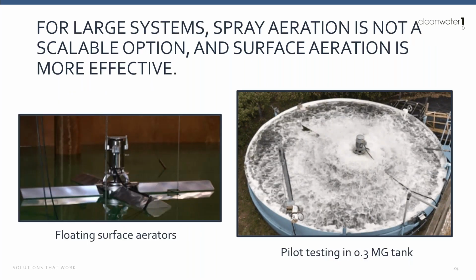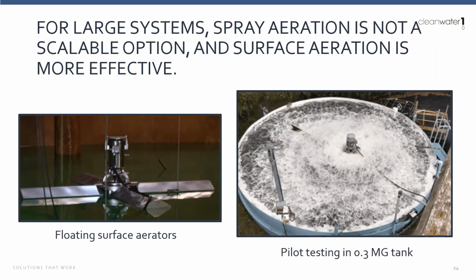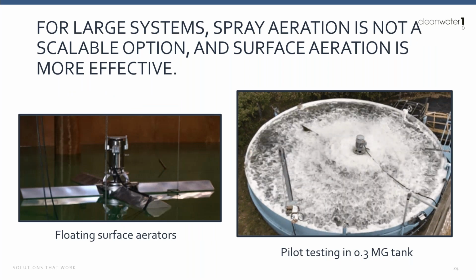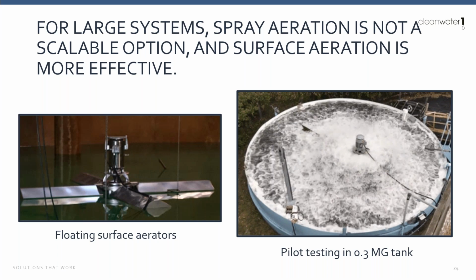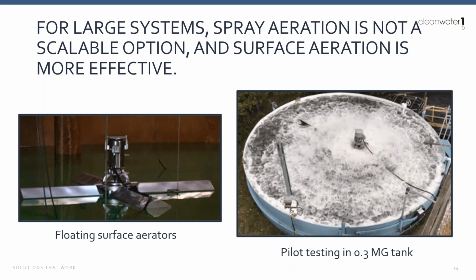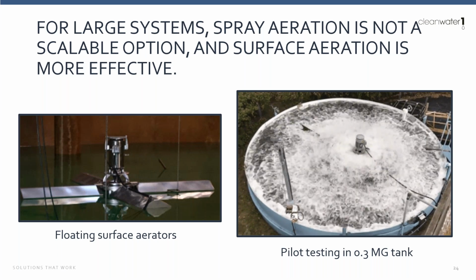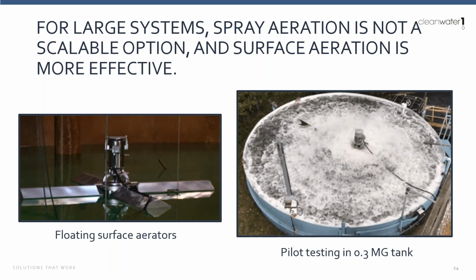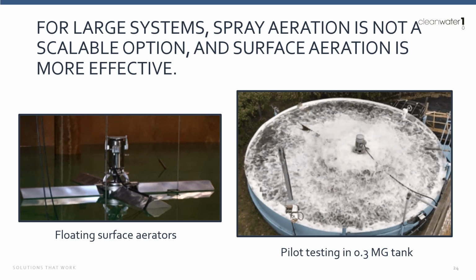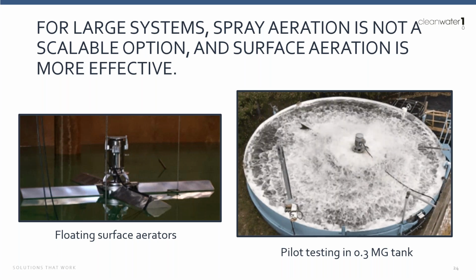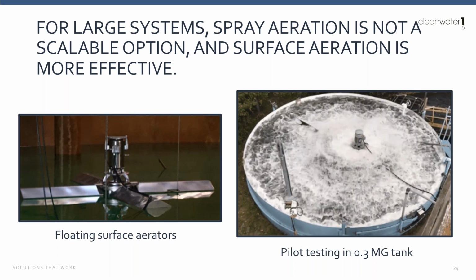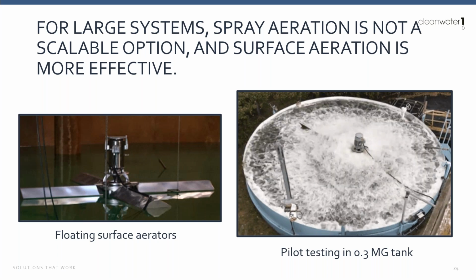As I mentioned, we've had a great partnership with Aqua Aerobics with their floating surface aerators. These surface aerators move a lot of water, and you can see the spray pattern here, where we're not spending our energy to pressurize the water and break it up into lots of little droplets with a ton of surface area. Instead, we're creating a froth of water.